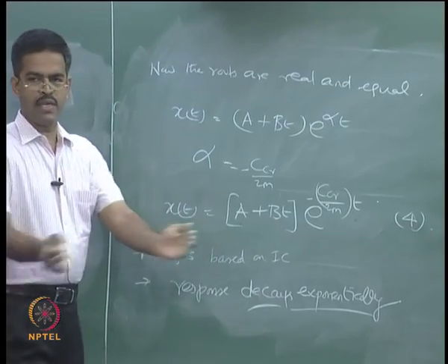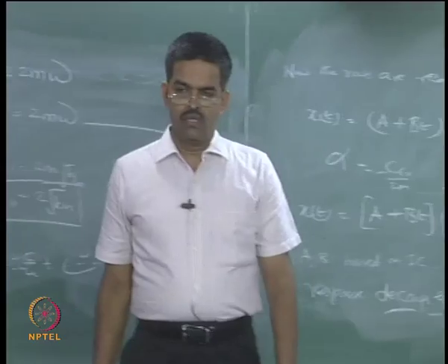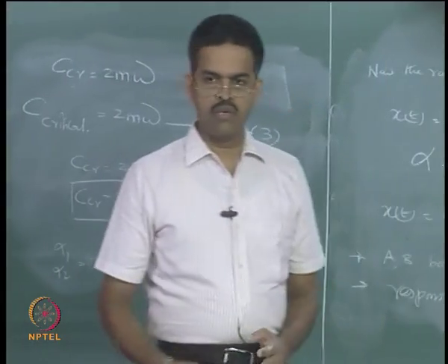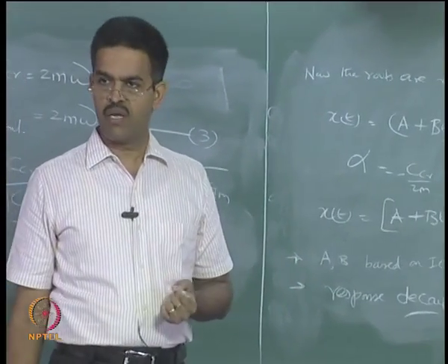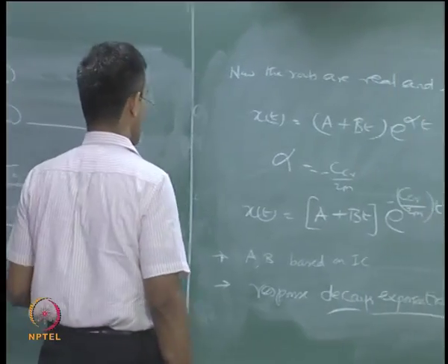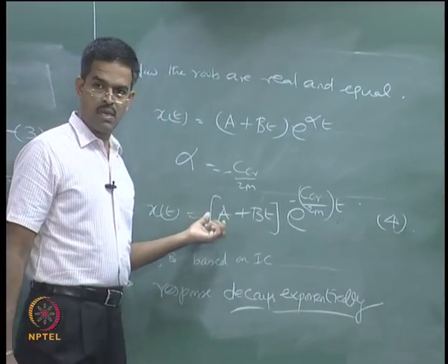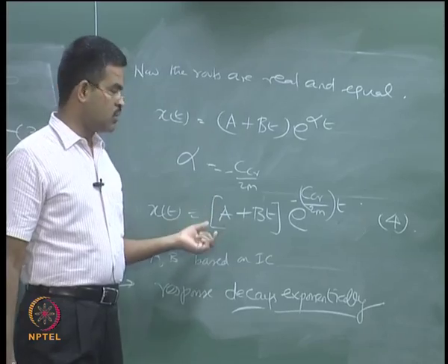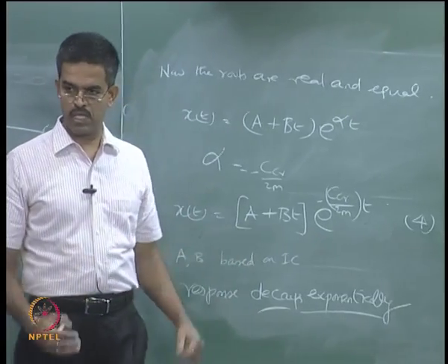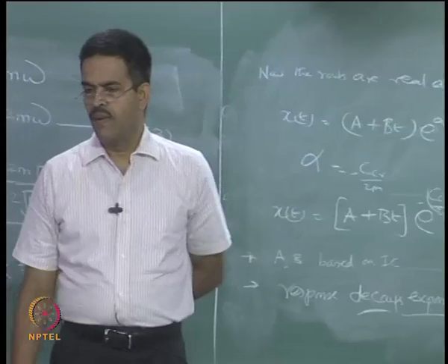So, damping is an inherent component of my single degree of freedom system model, I cannot eliminate it because it shows me an unrealistic behavior otherwise. So, I have to include damping, and in this model I have picked up viscous damping. I will speak about Coulomb damping slightly later once I complete this exercise.